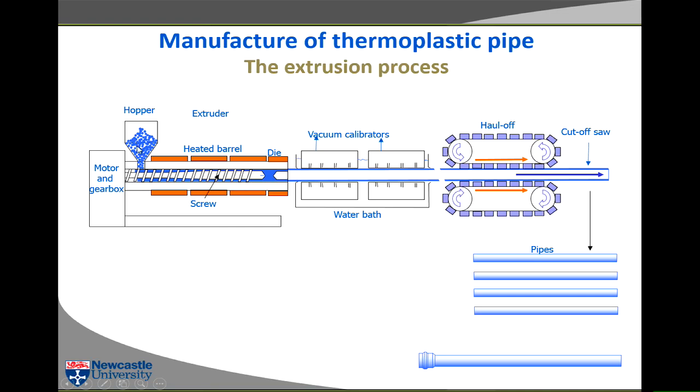You feed the granules in at the back end of the screw, and the extruder conveys the granules along this heated steel barrel. Whilst the granules are being conveyed, they're compressed and rubbed against the wall of this tube in the extruder. So you overcome the low thermal conductivity by pressing the material against the hot steel wall and rubbing it along the wall.